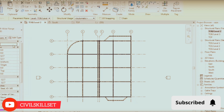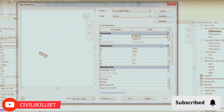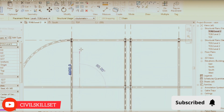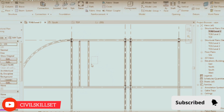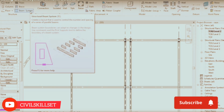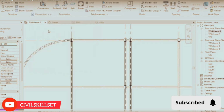For example, this metal beam I just duplicate it, right? For example, 15 and 25. I type it here too. Well, now, I really need to place each of these one by one. It seems complicated, right? To place all these beams one by one. Well, luckily, there is a tool in Revit called Beam System that does the placing of the beams in these spaces. But you need to have already loaded your beams, and it just sets it for you. It places it for you.